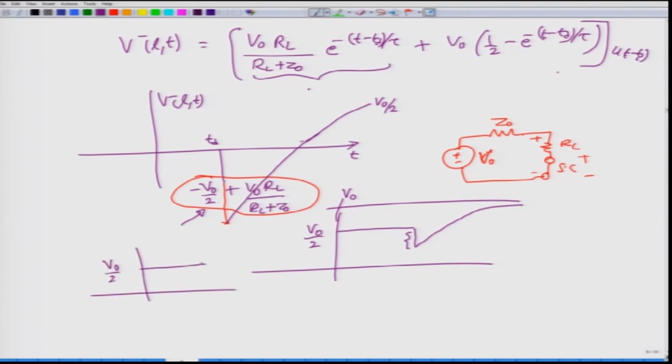On the other hand, if you obtained a voltage waveform that looks like this on the TDR, which would not completely jump up but only jumps slightly up, and then eventually goes to 0, you know that this should have been the complete jump had only an inductor been present. However, because there is a gap now, this would more likely be an inductor in series with a resistor. So there will be RL and some LL indicating a load, that is a series combination of R and L.